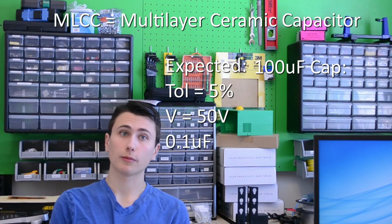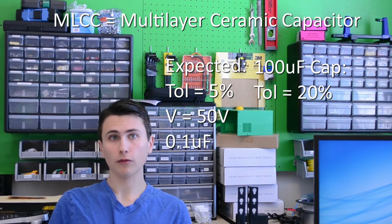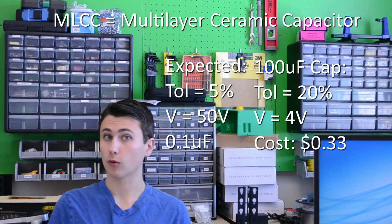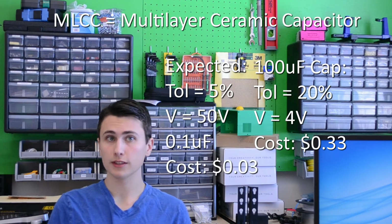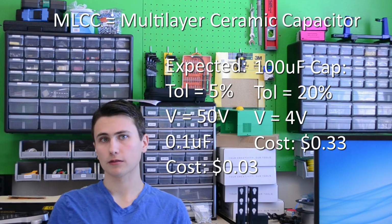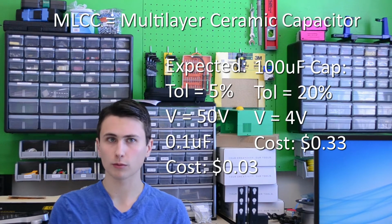The 100 microfarad capacitor has a 20% tolerance instead of 5. It has a 4 volt rating instead of a 50 volt rating. And the larger capacitor costs 33 cents per unit at a quantity of 3,000 instead of 3 cents at a quantity of 4,000. Now in order to increase the capacitance from a value of 0.1 microfarads to 100 microfarads, or